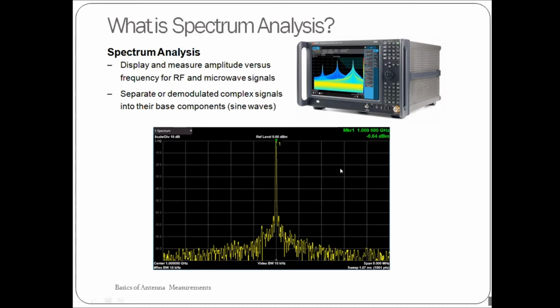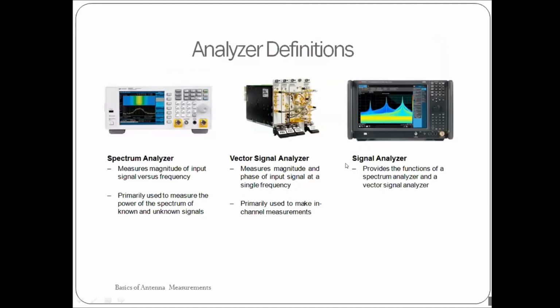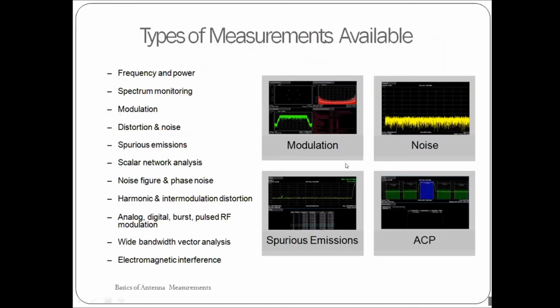You see, why I am showing this is, all the measurements we will see in dBm, because the connector is with respect to 1 milliwatt only. So it is showing dBm, and the frequency is also shown. If you select a marker, it will pick up a peak signal and show it on the reference. These are all the measurements,